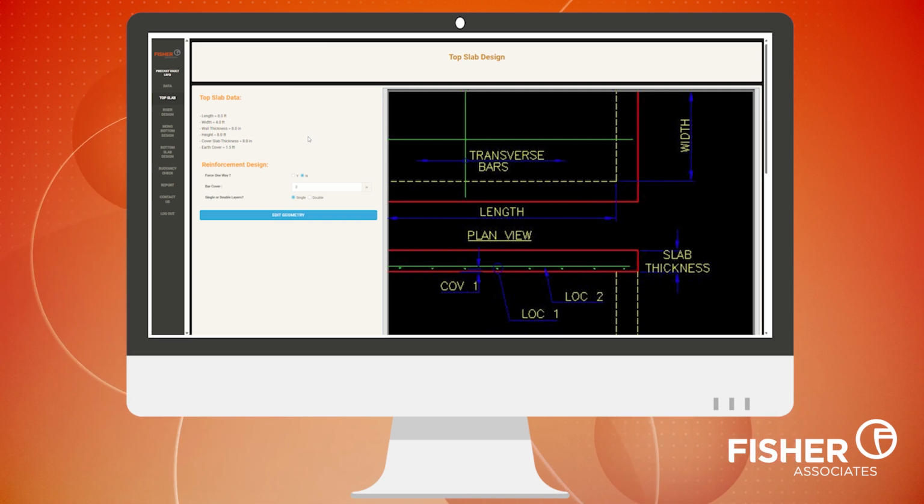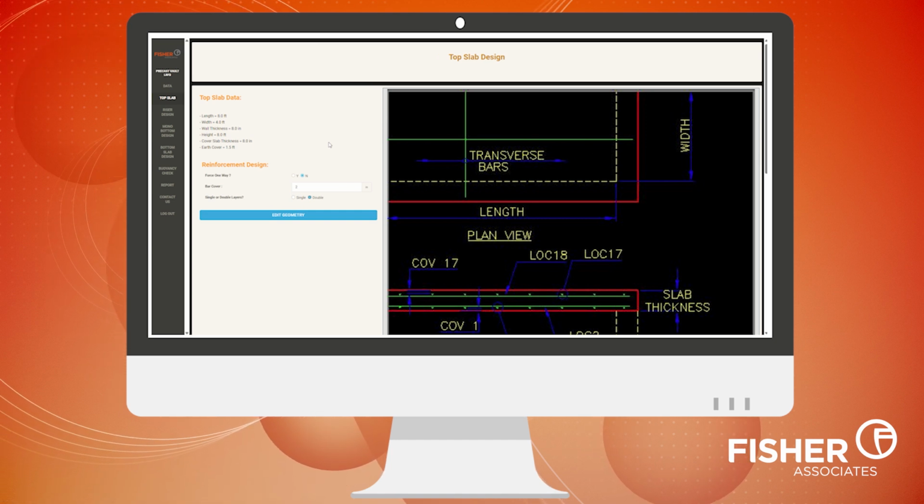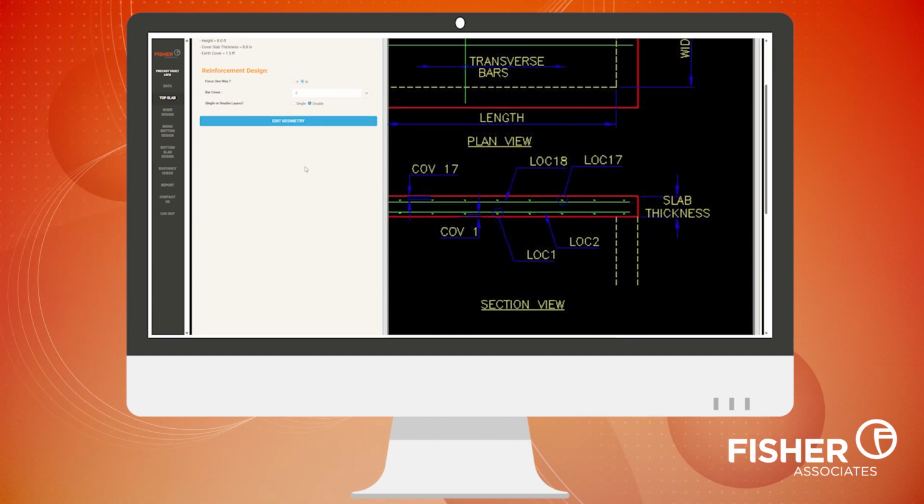Next, the system will ask if you need single or double layers of reinforcement. For instance, according to NYS DOT standards, if the top slab thickness is 8 inches, double layers of reinforcement are required, meaning you'll need 2 layers in your design. As shown on the plan to the right, you now have those 2 layers visible.